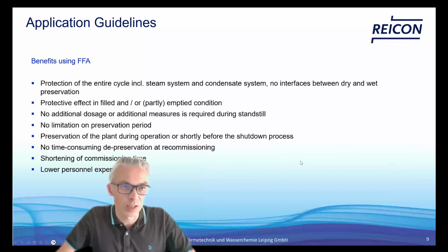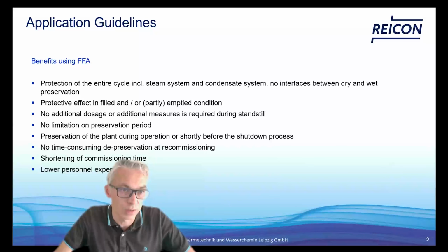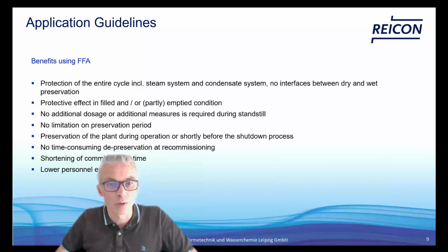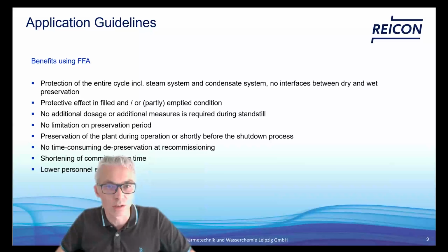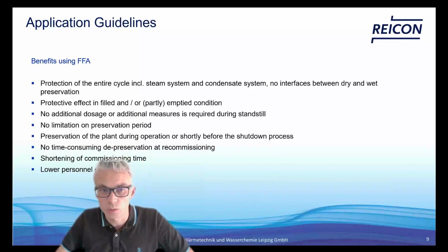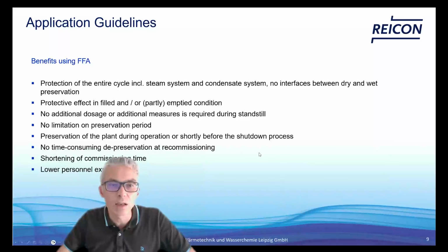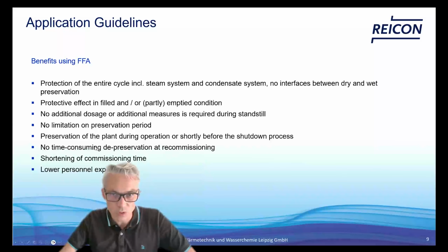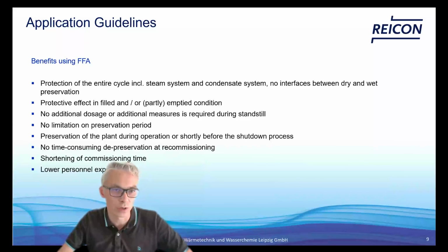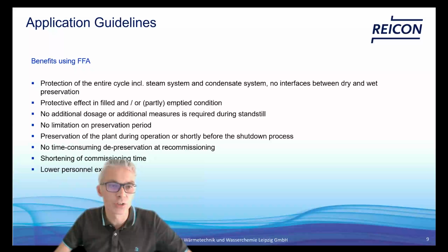Also, the protection effect is given in a filled situation, or if you empty and drain the water from the system, or if you have areas where you cannot drain the system completely, then also there you get a good protection of the surface. During the standstill, there are no additional dosage or measurements necessary. The surface stays protected within the standstill period, and there's no limitation on that.